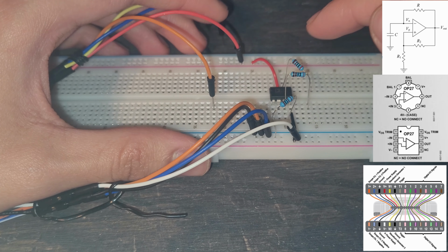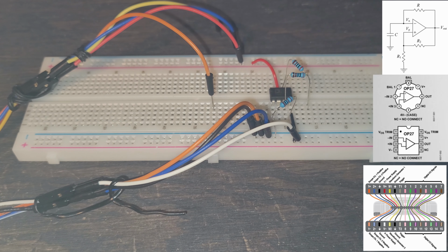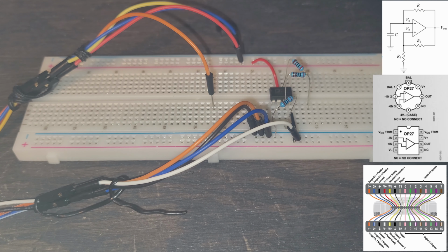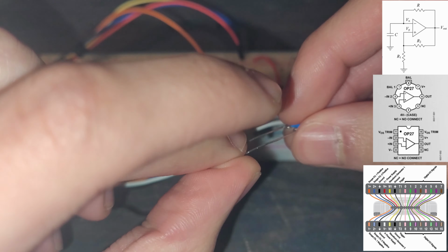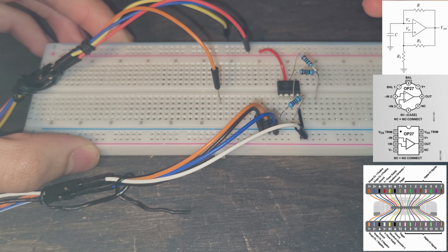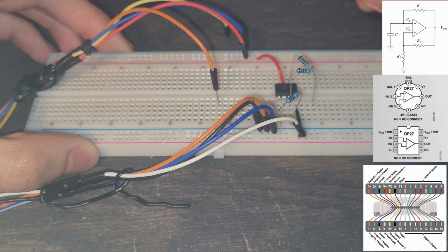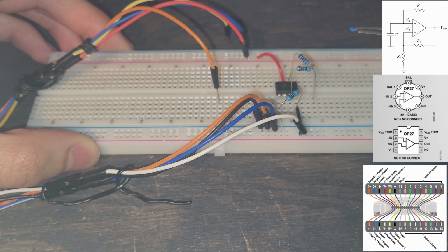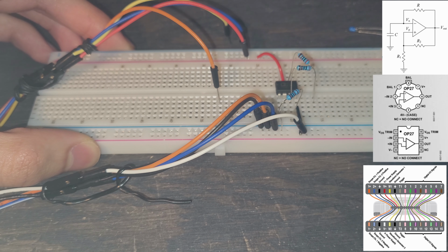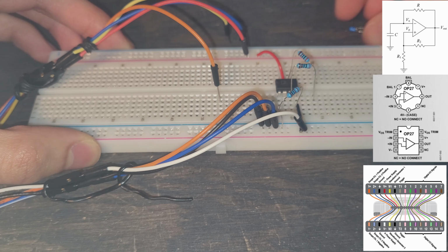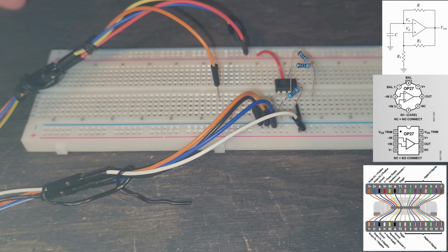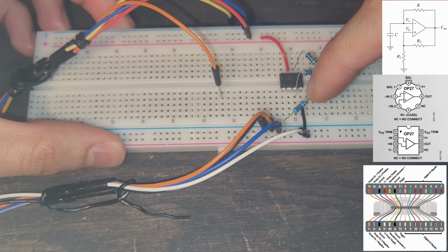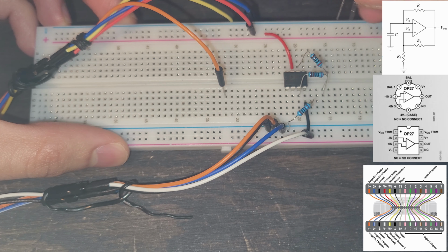Now, again, my partner and I seem to be very unsure about this resistor, so we're just going to add the capacitor and see how that looks. So the capacitor is about 4.7 nanofarads, and we're going to take this little guy and connect it from the ground to our Vin, and we can see that from the little diagram we have here. And our ground is going to be the negative rail right here, and we need to connect that. We need that to get to the V negative, which is that second pin right there.